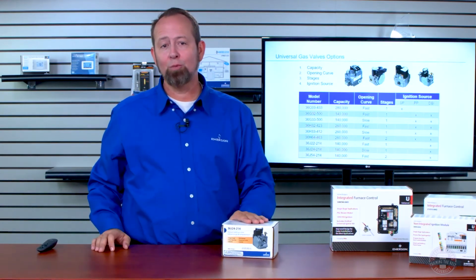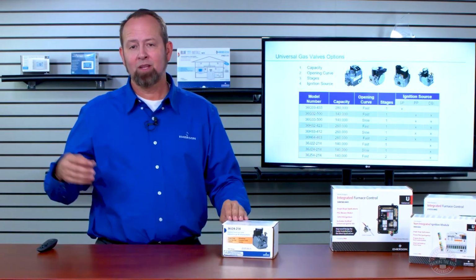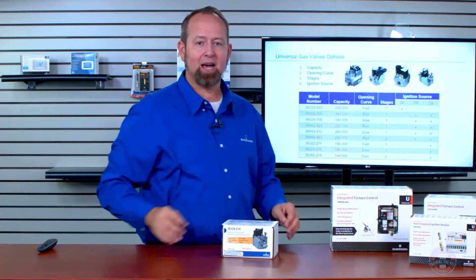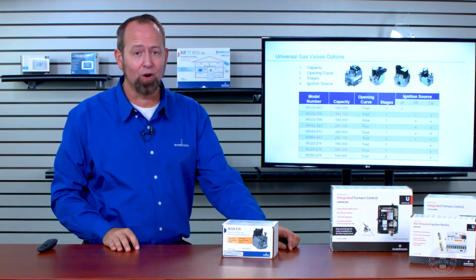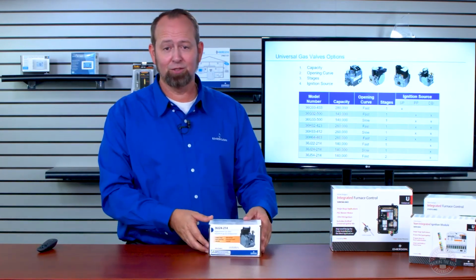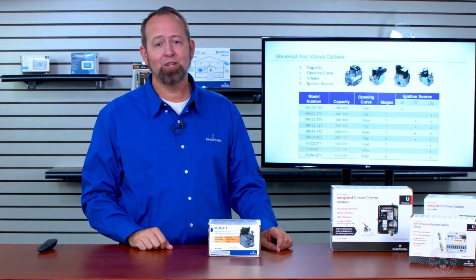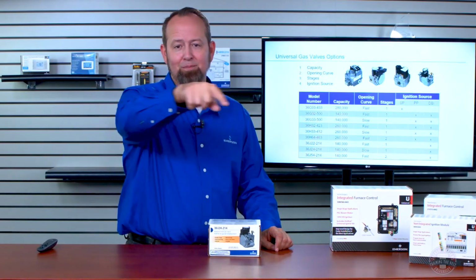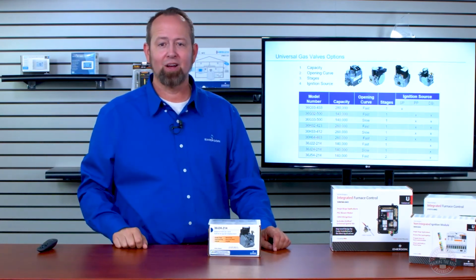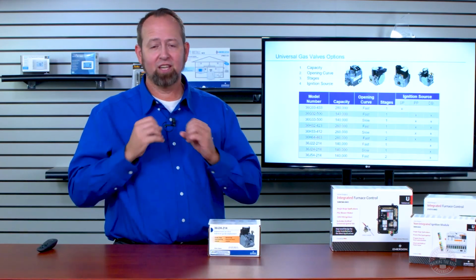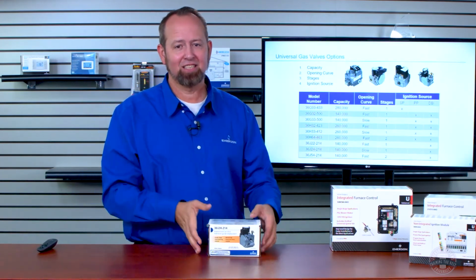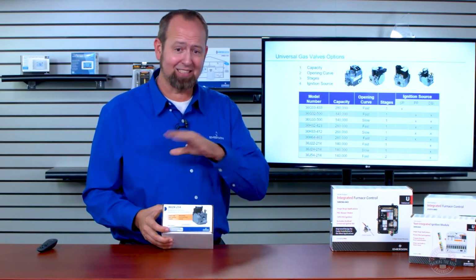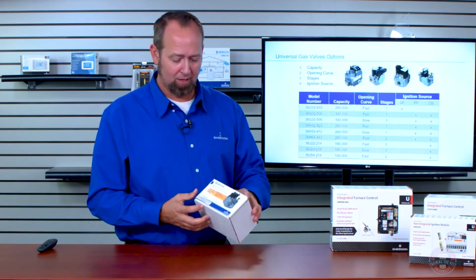So a slow opening valve was required so that as that gas came in, it would ignite all the way back through the whole burner. Similar to, again, the gas barbecue, where you turn it on and you actually see that ribbon or that fuel slowly go around it. It's not forcing a whole bunch of gas out there instantly. It's going through at a slower pace. So that's the difference between fast and slow.